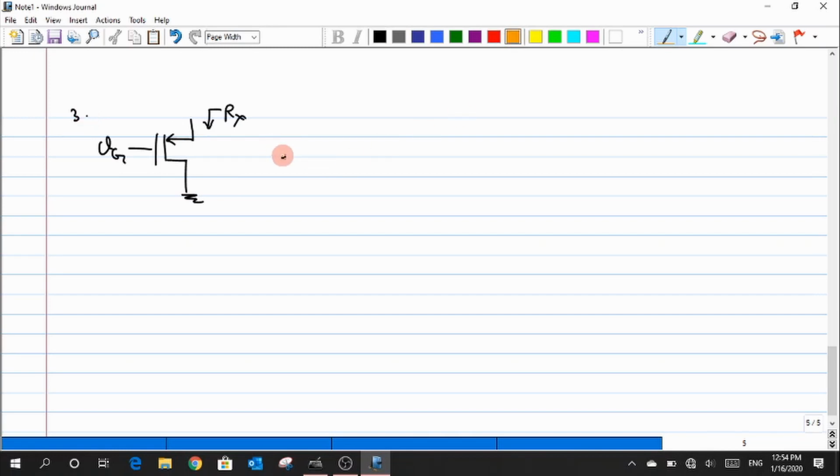Okay, so I again begin with drawing the small signal model, starting with all the 3 points of my gate, source and the drain. According to the circuit that has been given here, the drain is available at the bottom and that has been connected to the ground. So I just connect that node directly to the ground, and what is connected over here is just VG. I'm going to consider a positive potential across the gate such that the source will become a negative potential.